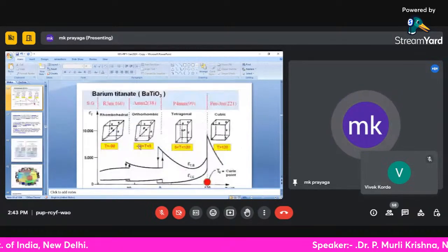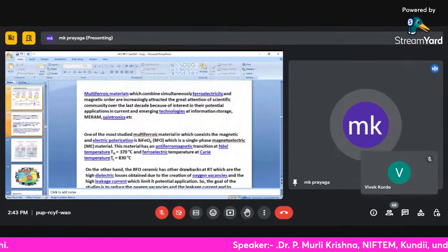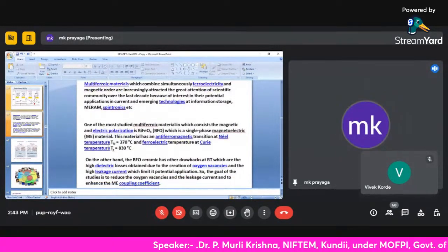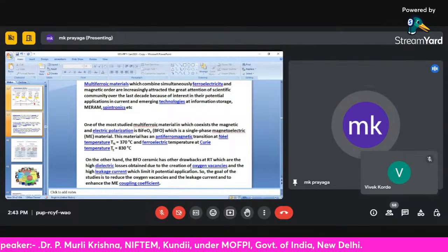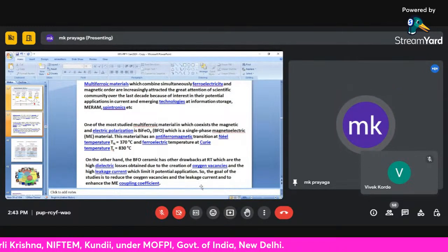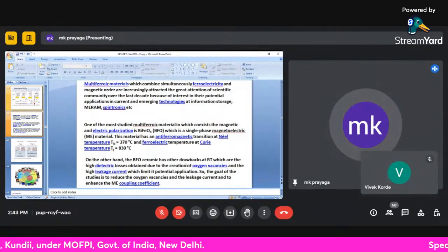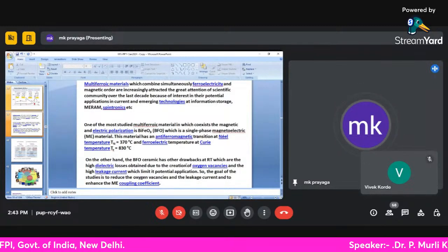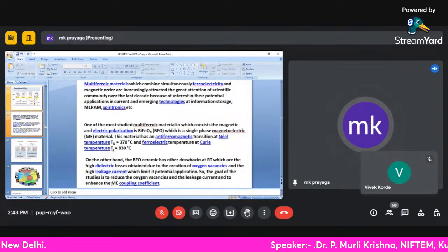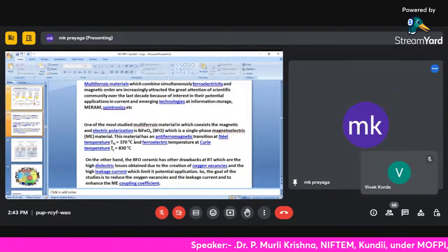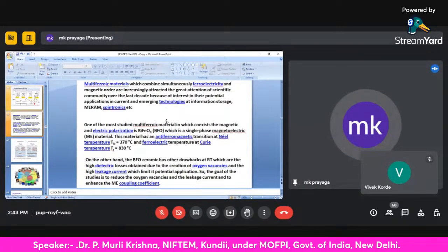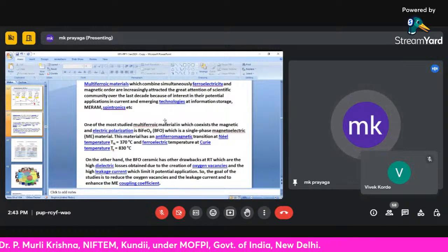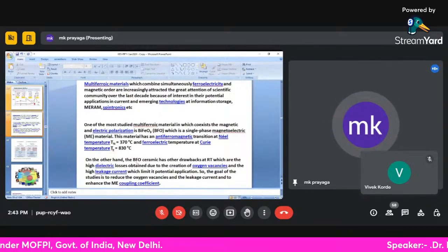And of course, when you are designing these multiferroic and ferroelectric materials, you have to choose various properties. Here, for example, I have given oxygen vacancy arrangements. If you can choose this, your magnetoelectric coupling factors will change. Even in ferroelectric materials, mechanical coupling factors, d33 coefficient, k11 factor, those kinds of coupling coefficients, you have to get very high values.